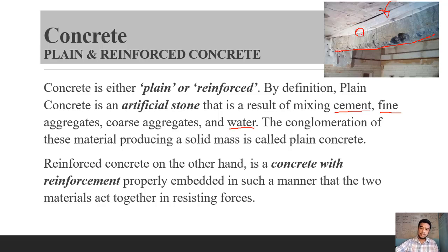Now, the upper fiber of this concrete is experiencing compression. Okay? When you, of course, bend a beam right here, the upper part experiences compression, and on the lower fiber, it is already stretching. Therefore, it is already resisting a tensile force. Okay? As I was saying a while ago, it is really very weak in tension. That is why they are reinforcing it with steel bars.